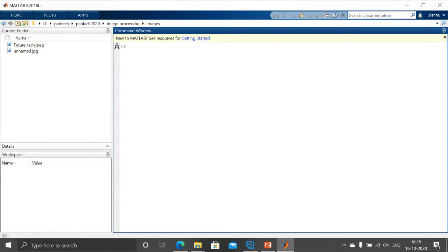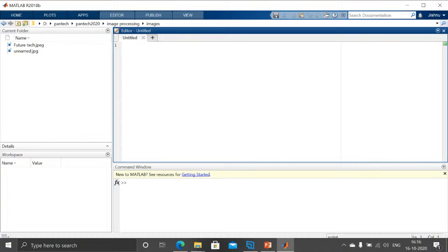Okay, so these are the live functions here. Here we will be able to work in the form of commands. So basically, to clear all the commands, I can provide it as clear all. Based on the previous output, all the outputs will be displayed over here. Then if I provide CLC, I can clear all the commands present in the window. If you want to provide any coding, we can use this editor option over here. Here we will be writing the entire script of the complete code.